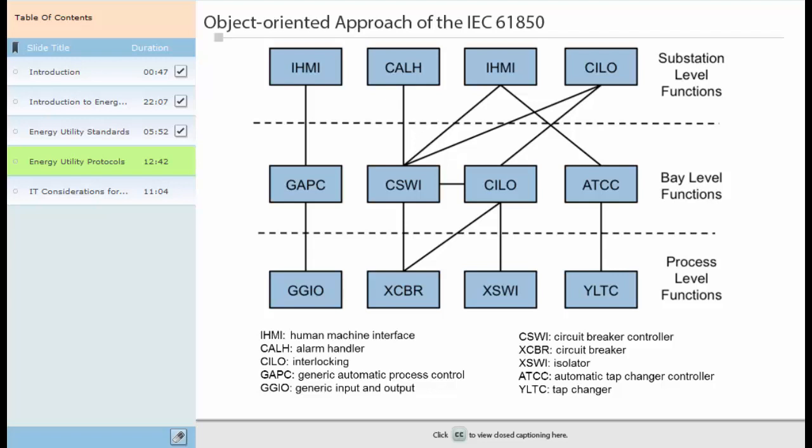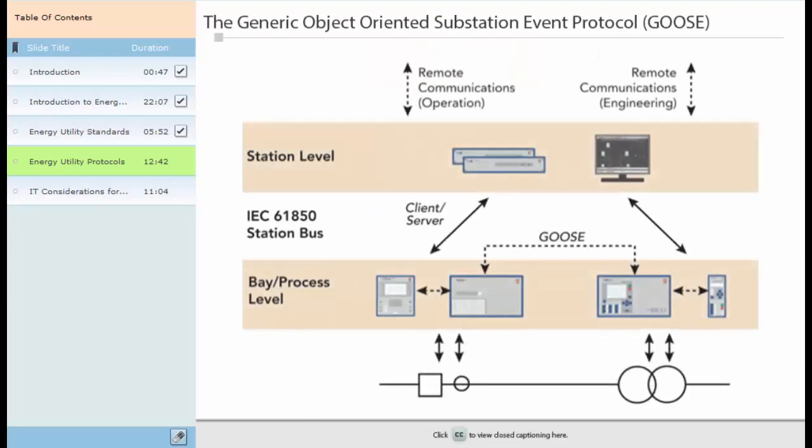Despite a number of advantages over Modbus, IEC 60870-5 and DNP3, IEC 61850 has additional implementation overhead. It is significantly more advanced than its legacy counterparts, which is why implementation has been slow to take off. IEC 61850 determines many services for the data objects of the logical nodes.